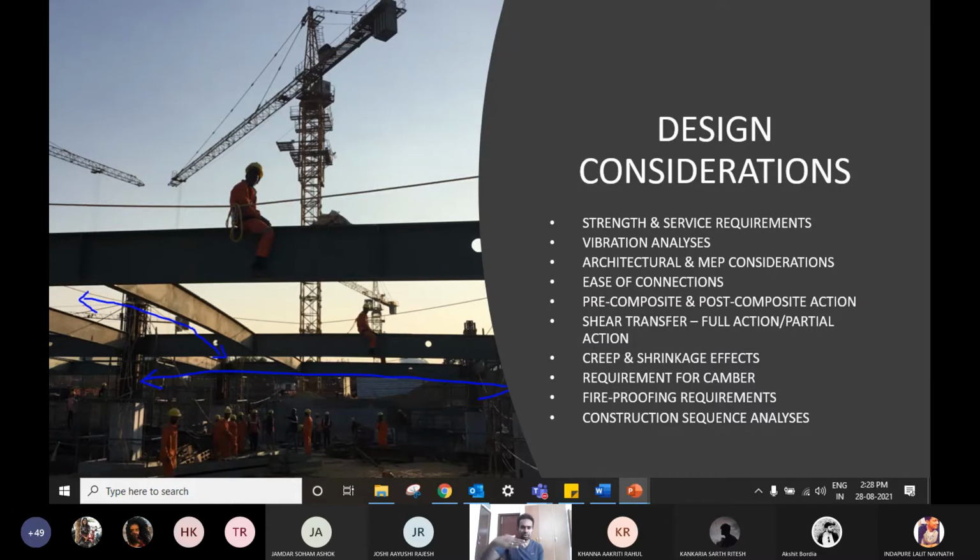So if you put something flat, it's going to deflect down. If you're going to make something inherently cambered on the top, then for the service loads, it's going to come down. For the extreme loads, it's going to come down a little bit, but it's not going to deflect as much as the case without a camber, right? So that's the purpose of a camber.